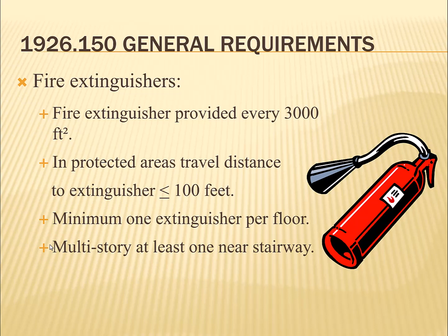And you should have a minimum of one extinguisher per floor. And of course, more if you've got huge square footage. And then at the stairways, you have to have an extinguisher at the top of every stairway. So by the time you satisfy that, you end up with usually more than one every 3,000 square feet, at least.